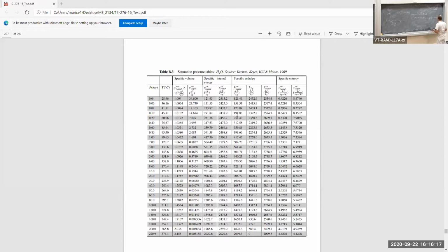I'm going to convert that into megawatts. 1 megawatt is equal to 1,000 kilowatts. So the kilowatts cancel, and I divide that by 1,000, and I get 10.18 megawatts. So the shaft work supplied by the turbine is basically 10.2 megawatts. That's how much power is being produced by this thing.